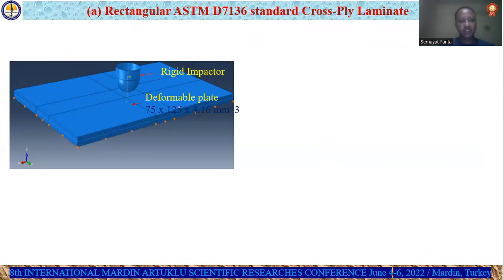with a deformable plate model and a rigid impactor model. And the dimension is 75 by 125 by 4.16 millimeter. This is the standard dimension I took.